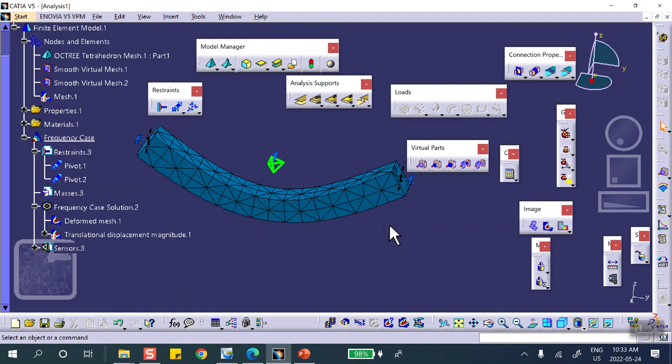You see, you have to look at that 1500 was based on the assumption that, let me put it this way. Here, when I put a pivot, that means that this end cannot actually shrink. Notice that there are different things here. One of them, you can't see it from that distance, but there is a fixture here that prevents this thing going back and forth this way. But there are other ones that are not like that. So changing those numbers will change the results.